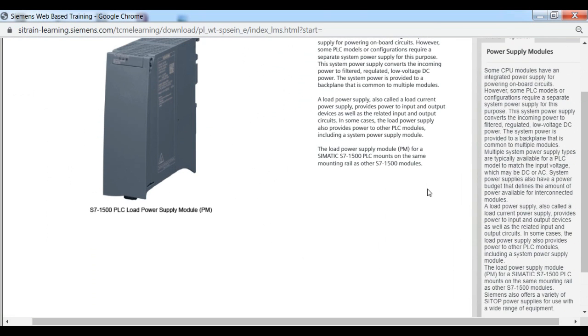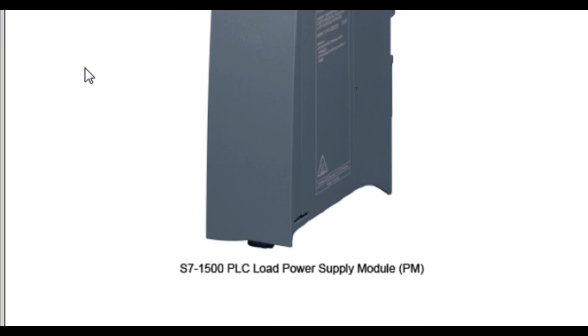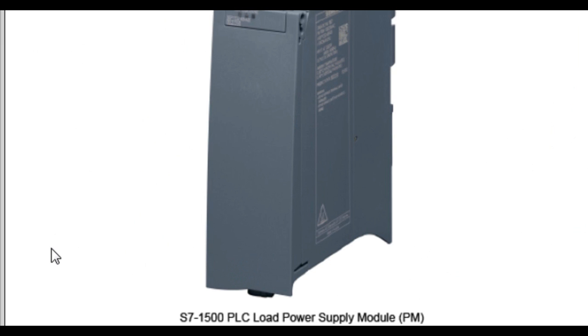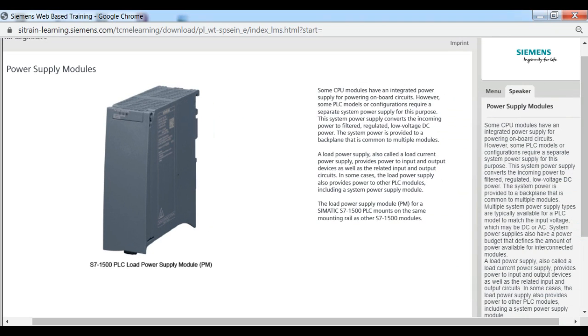A load power supply, also called a load current power supply, provides power to input and output devices as well as the related input and output circuits. In some cases, the load power supply also provides power to other PLC modules, including a system power supply module. The load power supply module, PM, for a Siemens S7-1500 PLC mounts on the same mounting rail as other S7-1500 modules. Siemens also offers a variety of SITOP power supplies for use with a wide range of equipment.